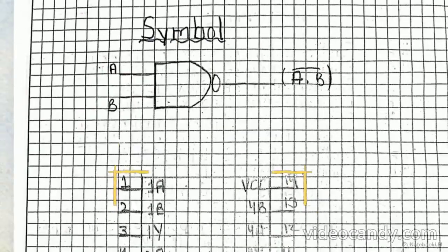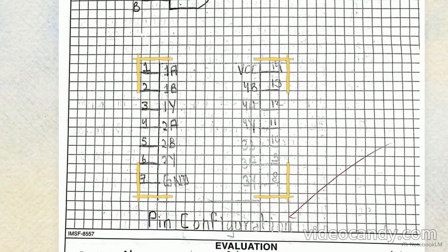We can see the physical reality of a universal gate by looking at this lab sheet for an IC7400 quad NAND chip. The hand-drawn chart maps the 14 separate pins required to integrate this gate into a wider circuit. Before assessing logic, the chip requires operational power. Pin 14 must be wired to the supply voltage, labeled VCC, carrying a positive 5-volt charge. To complete the circuit, pin 7 must tie directly to ground, securing the 0-volt reference point.